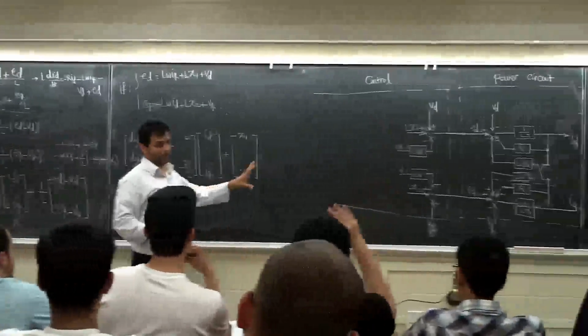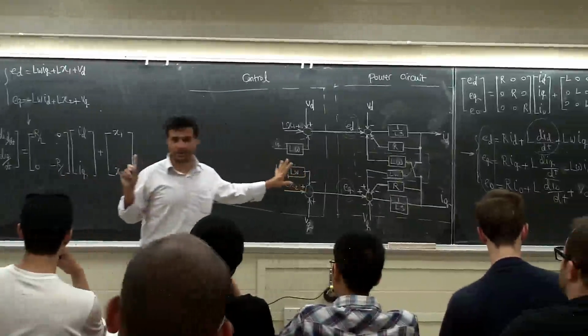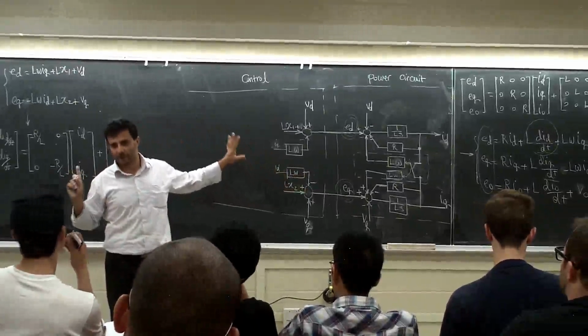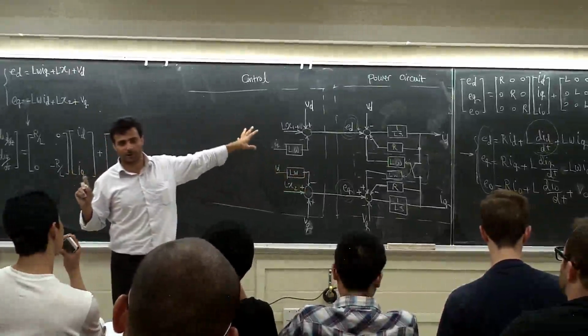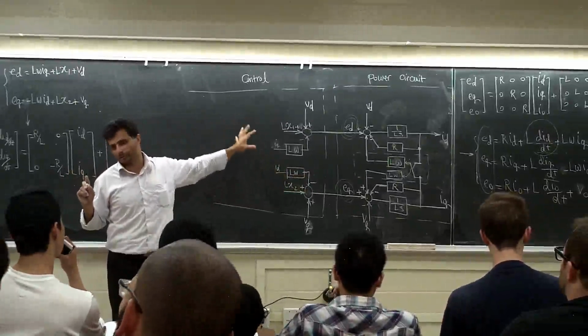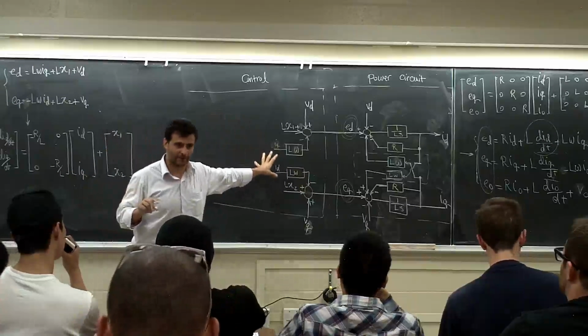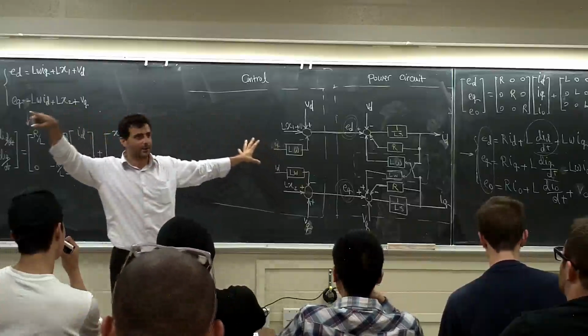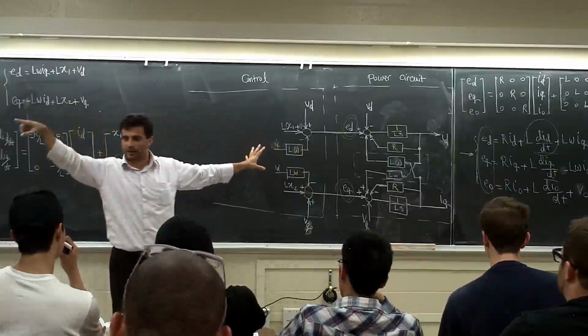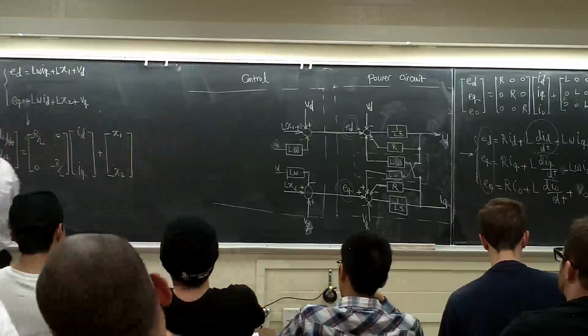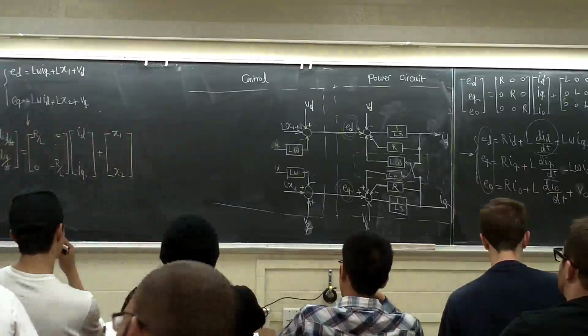Now, this is for control purposes because we are going to select the KP, KI. Remember what I said in the last class? KP, KI. You need to have a system to go plot either the bode plot or root locus or whatever you want to design the system to be critical damping, to have the fastest and overshoot-free system. That's what we are doing here. Let me finish this one and we'll talk about it because now we're right in the middle.